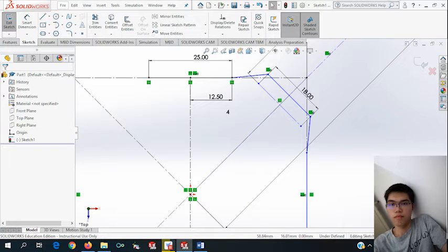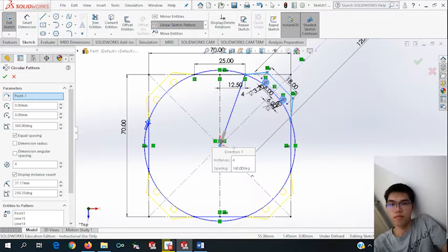Step 6, set the 18 mm line to construction geometry and create another 18 mm line on top of it. The gap is 4 mm between each other. After that, join the lines beside it by drawing lines. Step 7, draw 2 circles with a diameter of 3.2 mm at the construction line and set a distance of 6 mm from the circle to the center line. Create circular sketch pattern and choose the joined line and 2 drawn circles to be copied to another direction.